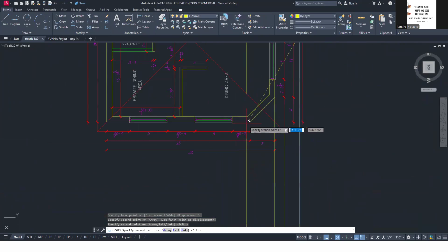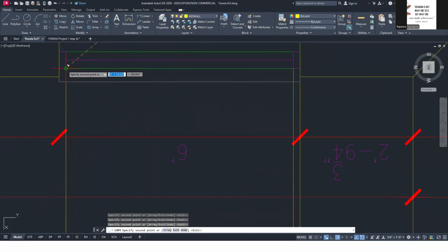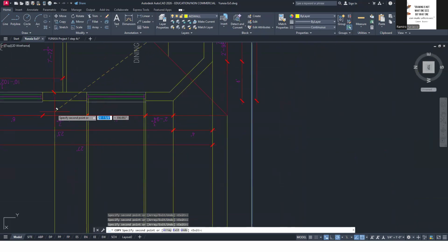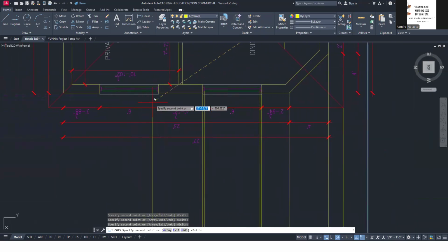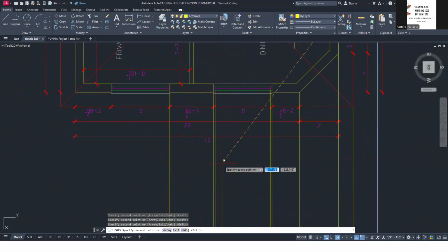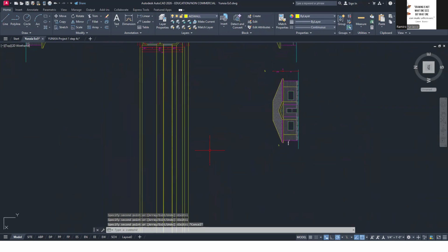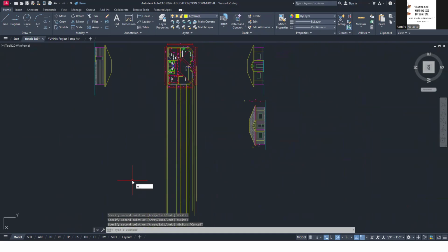Okay. And then, like earlier, you copy this. Now, do I need to project this? Here, I can just copy it once, and then I can use that as my reference to copy this window to that window right there, and then maybe to the end. And then likewise, again, best to do UCS view.